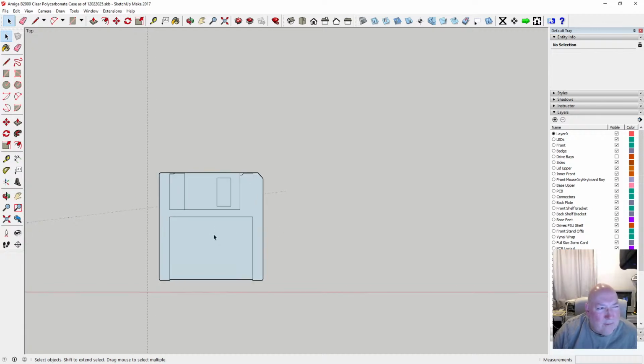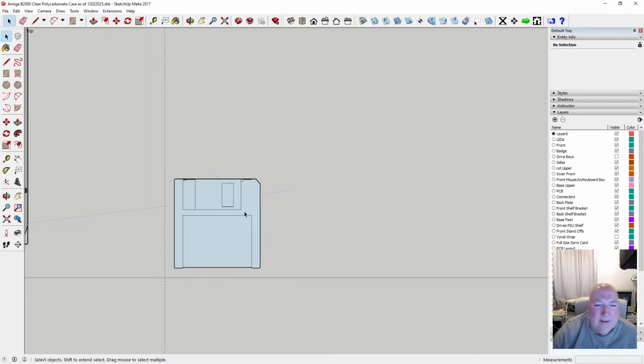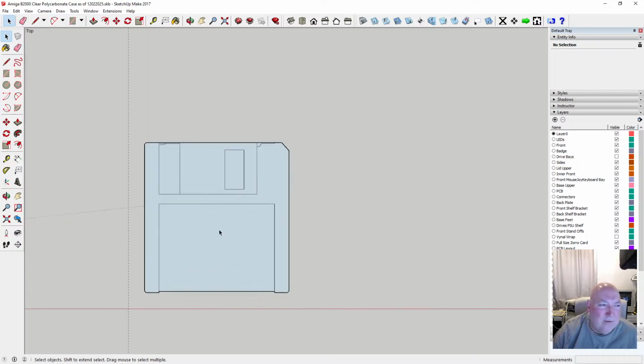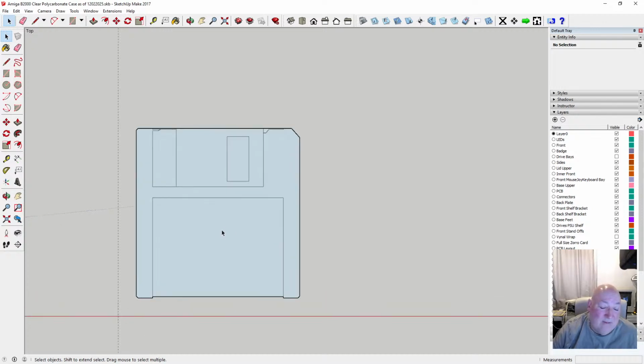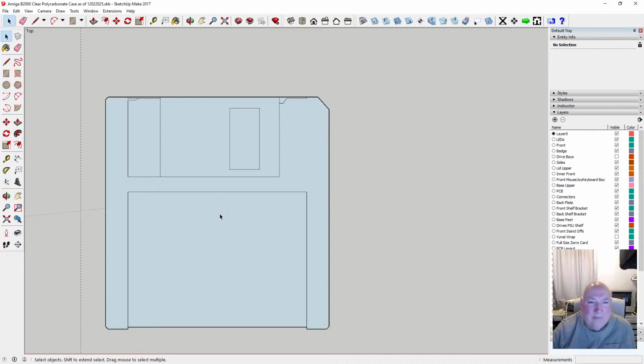A lot of people go on Raspberry Pis, you know. I've never needed to go onto a Raspberry Pi before, because one thing, it has to boot up an operating system on the SD card and run your program. SD cards can go wrong after a while, you know. You've got eMMC flash drives and all sorts now. It's gone up in leaps and bounds, but I've always managed with an Arduino Mega, and then moved over to ESP32, and never had any problems with that.